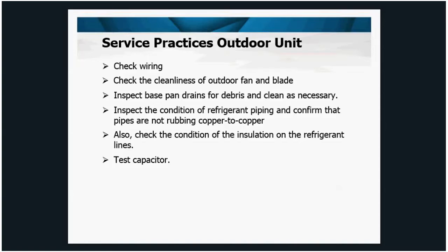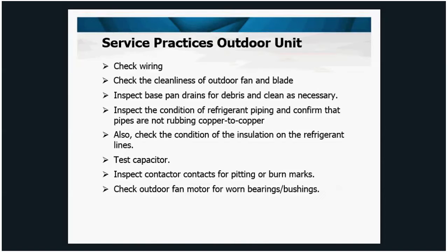Always do a capacitor check. Inspect the contactors for pitting and burn marks. We should also look for worn fan motor bearings. Now, these are the fan bearings in the outdoor unit. We'll do the same on the indoor unit. It'll come up in a couple of clicks.